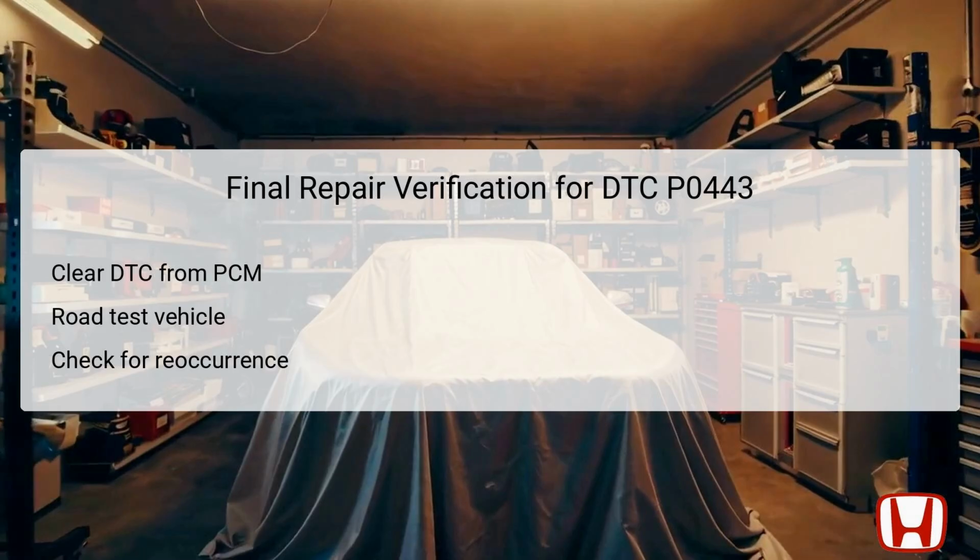After any repairs to address the DTC P0443, it is essential to clear the code from the PCM to reset the system. Once cleared, perform a comprehensive road test of the vehicle under different operating conditions to ensure that the repair has resolved the issue.